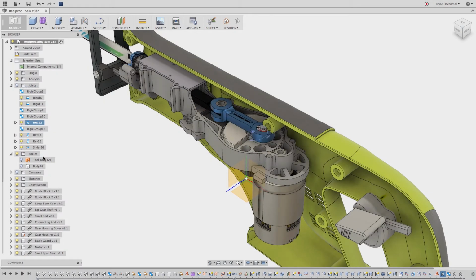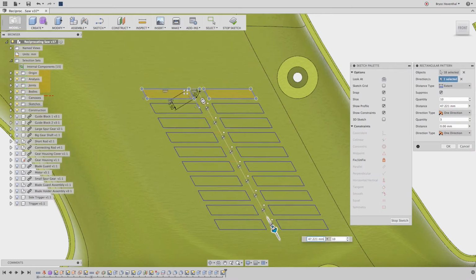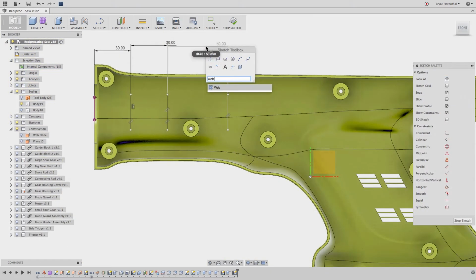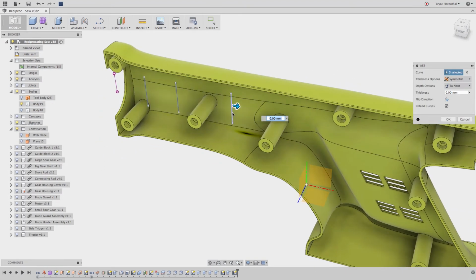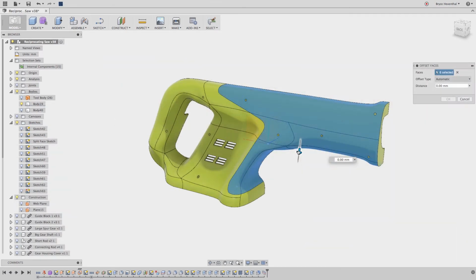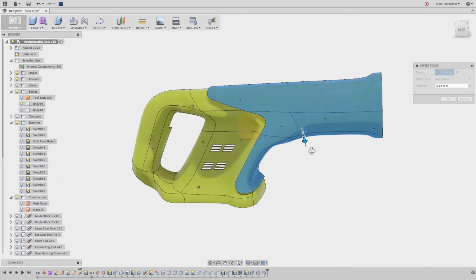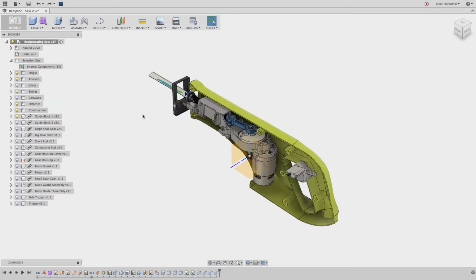Now that we are done creating our freeform surface, we will start by adding parametric features on the B side of this plastic housing. Usually this process is done in a completely different tool, which would require a translation. This means that updates to the surface do not propagate to the tool creating the parametric bosses, ribs, and cuts. In Fusion 360, we will demonstrate how these two separate modeling techniques can integrate broken product development workflows.